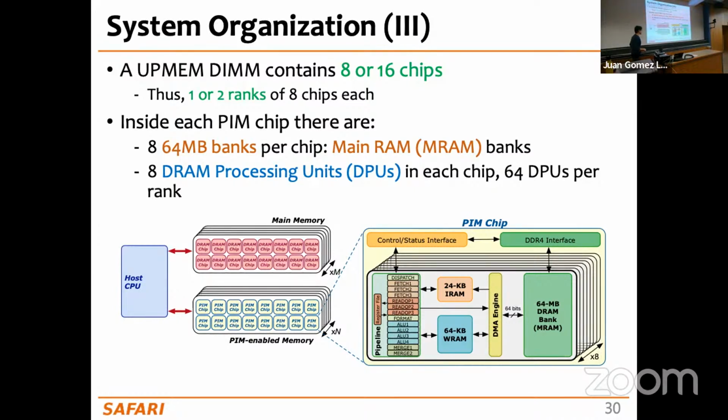As a first description of what you can see here in the DPU, there is a DMA engine. This DMA engine can move operands, data, between MRAM and this WRAM here, or instructions to this IRAM, that is an instruction memory. It's not an instruction cache, right?